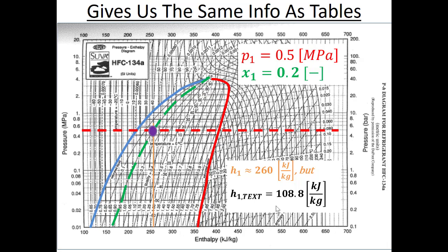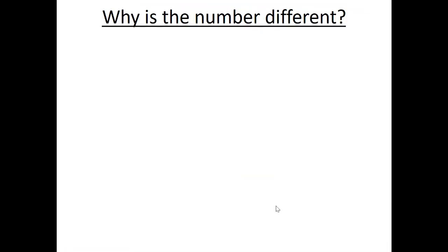So if you've got some storm rolling in, your atmospheric pressure is going to be different, but your gauge pressure always only measures relative to the local pressure of the atmosphere at the particular time where you're taking the measurement. So in this case, my H values are different because my datum, or my 0 point, is different, right?